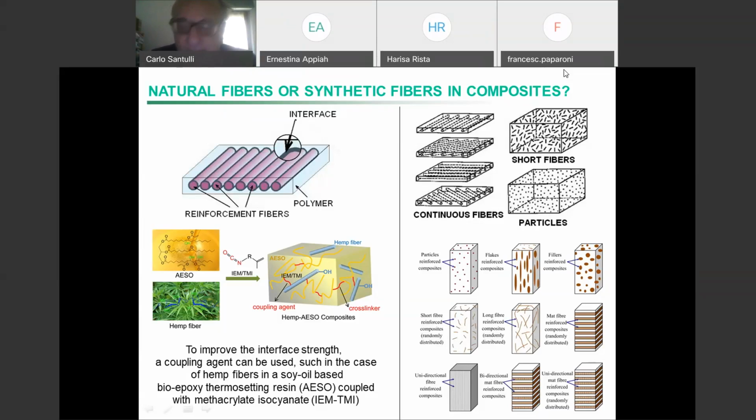Then you can have mats, which are produced by punching, by being punched basically. So you don't have a real weave structure. Easily think of your door mat, the mat most people have on the door. This is a mat which is not woven, but it has been punched in a way that the fibers stay together. But of course, they have a random orientation. If you look at your door mat, you cannot say that the fibers go in the same direction. Then you can comb them and allow them to go rather to some directions you like more.